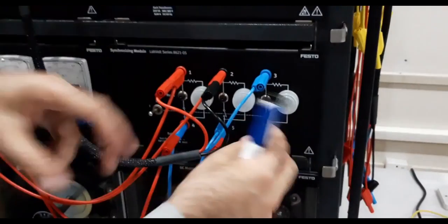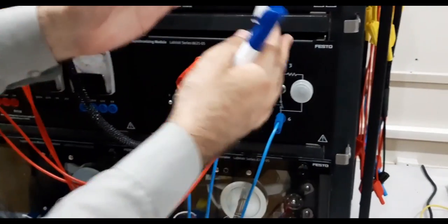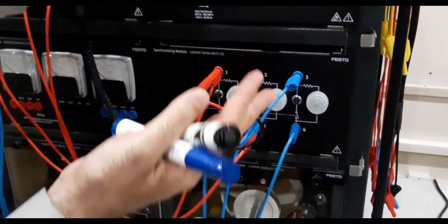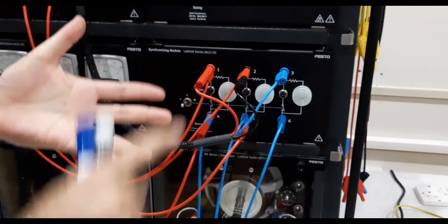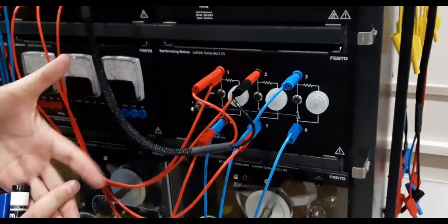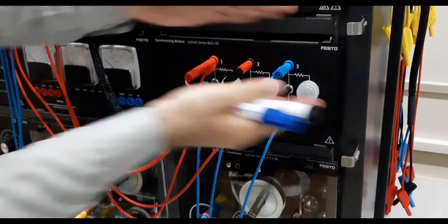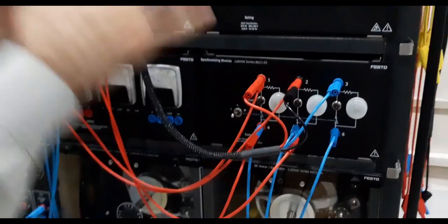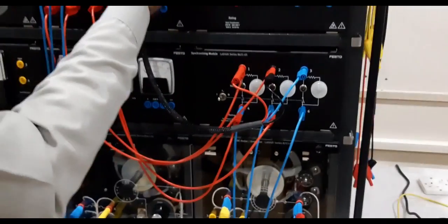And once we achieved that the voltage is the same, because there was no blinking of the lamps, we also changed the sequence, and then you also saw the blinking. So if there is no blinking, it will indicate that the conditions are fulfilled, where the phase magnitude is the same, the frequency is the same, the phase order is the same, and also the phase angle is the same. So once we achieve that condition where there is no blinking of the lamps, then synchronization is achieved. We turn the button on, and then the generator is connected to the system now.